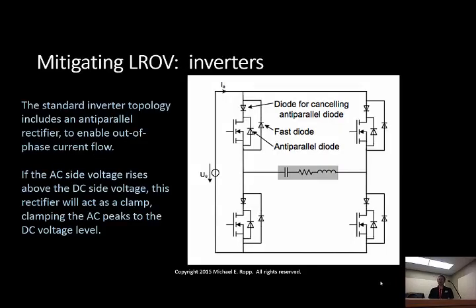Now, how about the inverters? We were talking about this before. We've seen what at first looked like some somewhat contradictory results. Why? This is a single-phase inverter bridge. I showed you a three-phase bridge before, and I've got a European example in here again. You see that the DC link voltage is labeled U. So apparently this is a German picture. But you'll notice that within the inverter topology, and I mentioned this back when I showed you the three-phase one as well, this one shows MOSFETs. But on each one of the semiconductor switches, there's a diode pointing the other way. There's an anti-parallel diode in there.